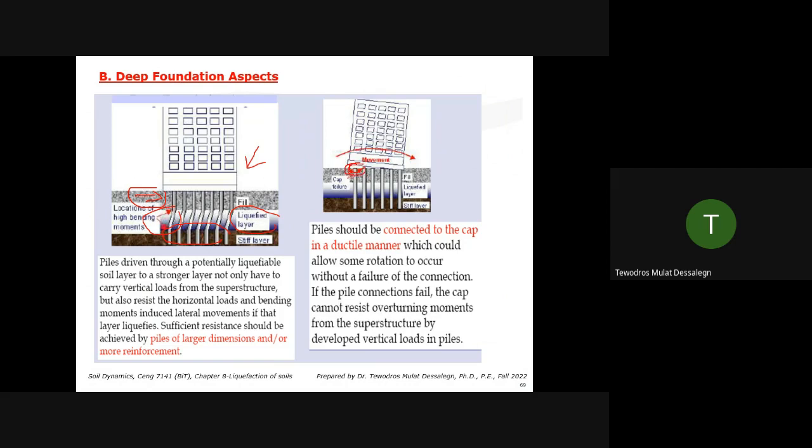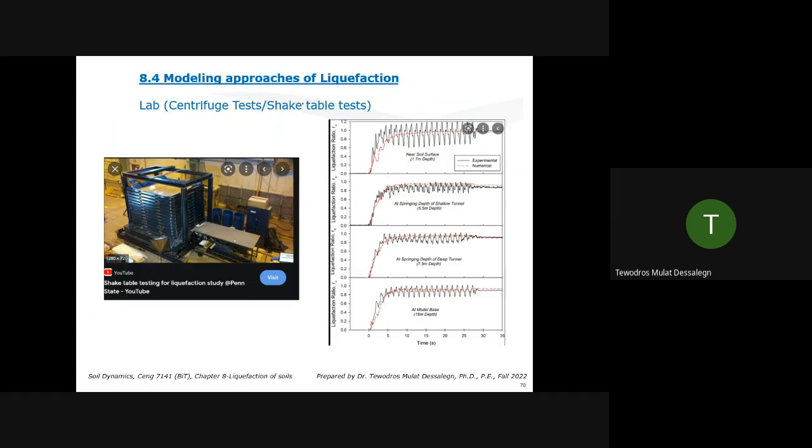Usually we don't design this pile cap connection for moments. It's like only pin supports. So there is some flexibility to move around. Or the best thing is like a batter pile you can use, diagonal piles, so they take out the lateral loads. Like offshore structures against hydraulic tides and things like that. We have only 10 slides, we can finish it. Or are you guys tired?